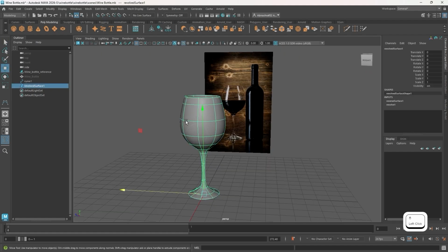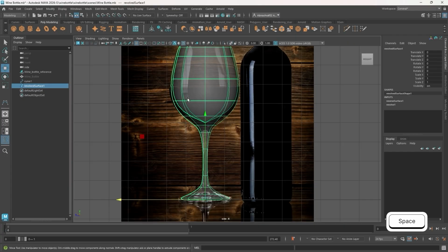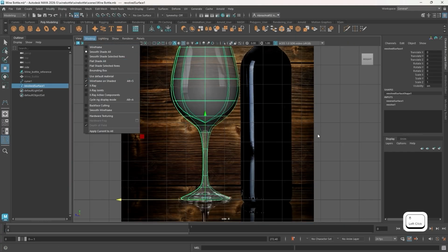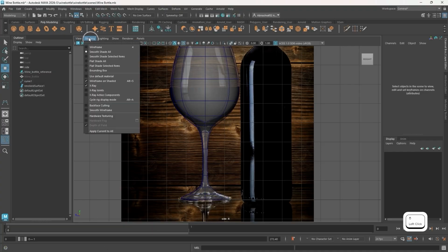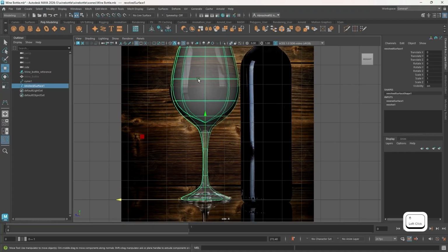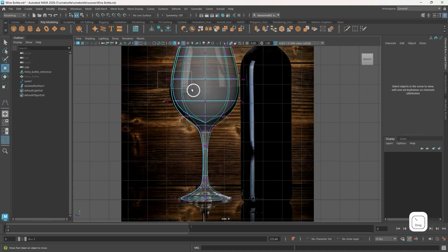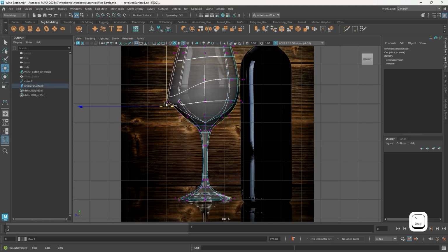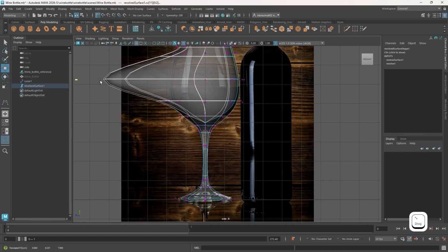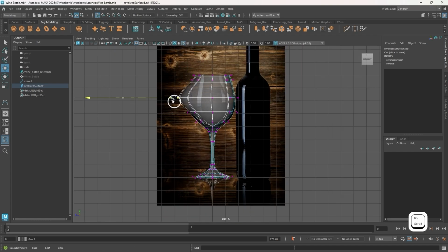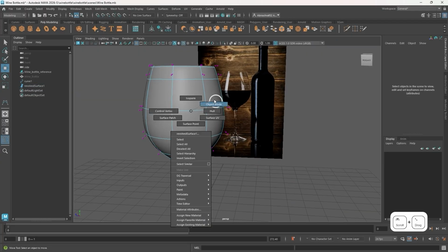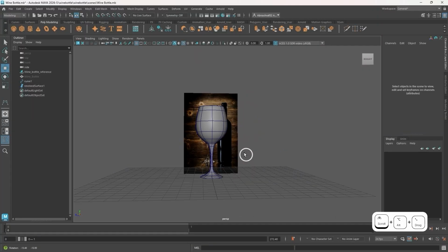Now if you ever want to edit individual parts of it, an easy way is to come back to your side, make sure your x-ray's on, and just go to Control Vertex. Then you can select each point and edit it if you want to. Now notice that the grid is not selected. If I were to select the grid, it will snap to the closest grid. It snaps every half pace. Let's go back, deselect it, and there you have your glass bottle, your glass cup.